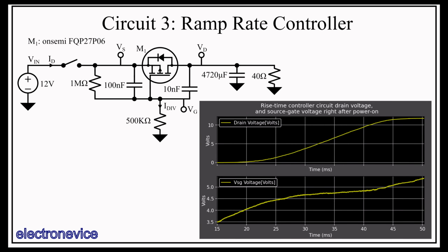Taking a closer look at the gate source voltage directly, since the gate voltage doesn't account for some of that source droop we were seeing, we see that the source gate voltage is not flat, and in fact, during the center of the rise time, it's sloping upward slightly. This breaks our assumptions significantly and causes a current to flow through the gate source capacitance. Since the gate source capacitance is much larger than the gate drain capacitance, then even though the VSG slope is gradual compared with the VGD slope, it will still present a significant error and slow down turn-on.